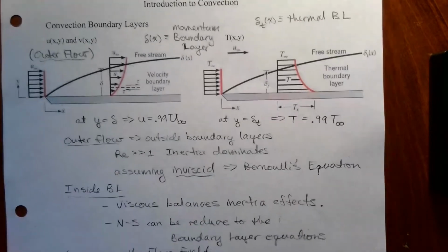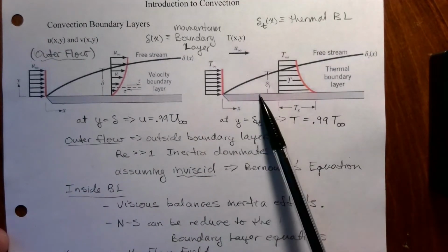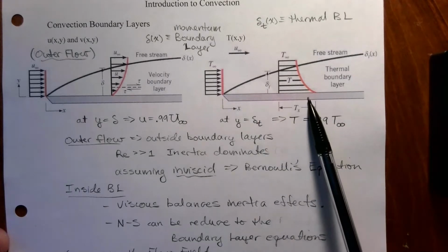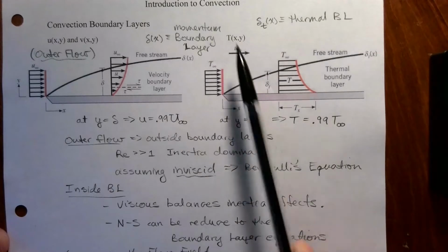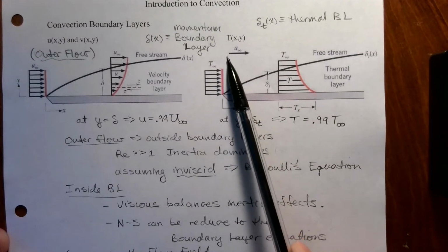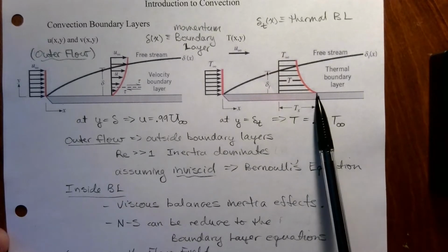Okay, so there's also a thermal boundary layer as well. Let's assume T surface is higher than T ambient. Far enough away from the surface, the fluid is at a temperature T ambient. Directly adjacent to the surface, the fluid temperature is the same as that of the surface.